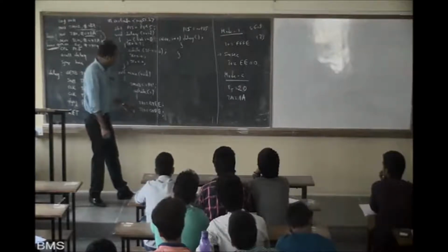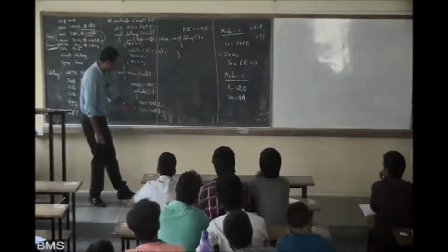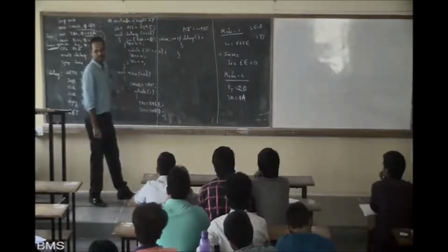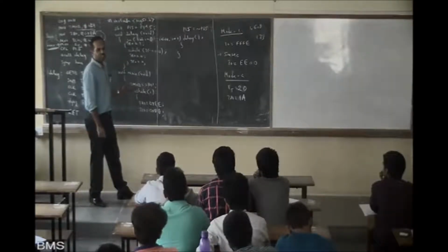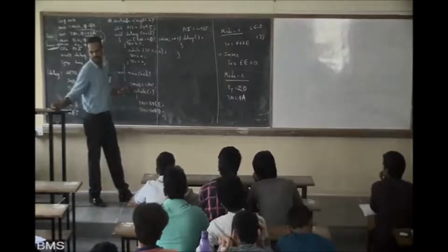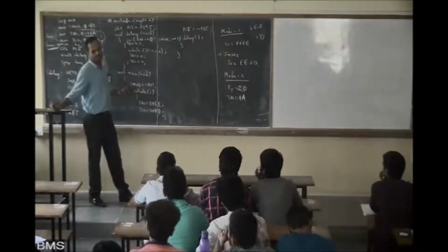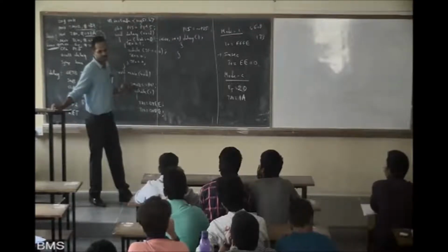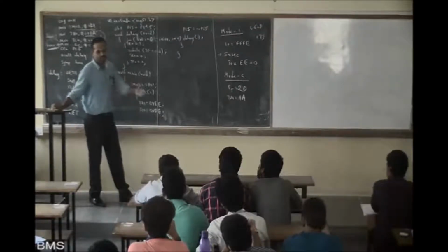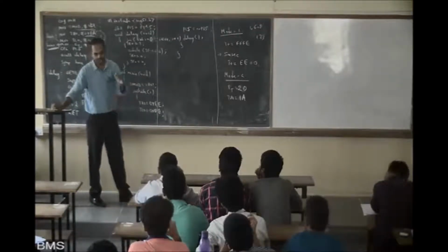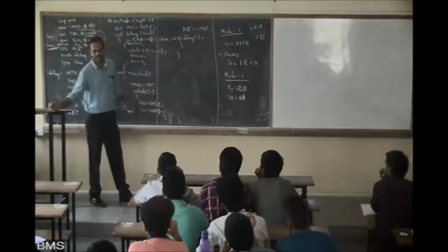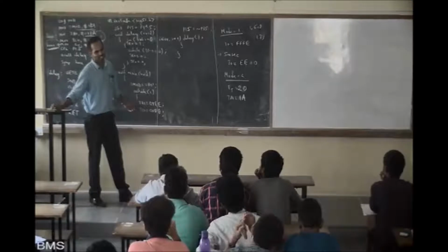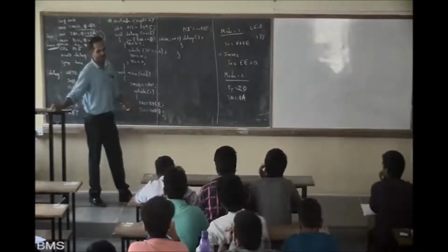In this, the values TH0 and TL0 can be pushed out of the while loop. When I say pushed out of the while, it is because mode 2 is the auto reload mode. Now if, as Harshit is asking, I write it, what happens? Nothing will happen. It will be like that only. Any doubt?